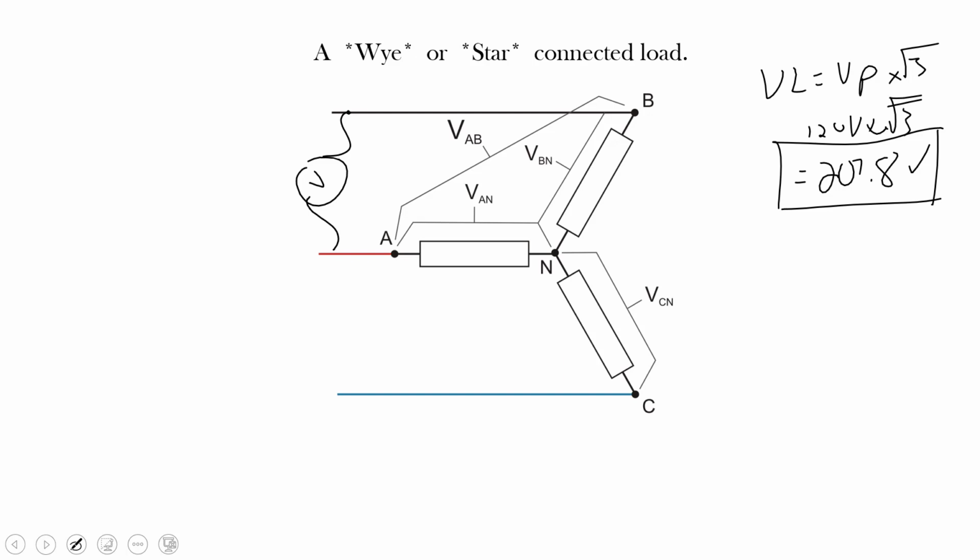And what we're going to do is walk the path that our voltmeter would see. So what do I mean by that? I'm going to write this out, VAB, a little bit differently. When I'm really saying what is voltage A to B, I'm saying what is voltage A to N to B. And what that means is I have to walk through what the voltmeter would see.